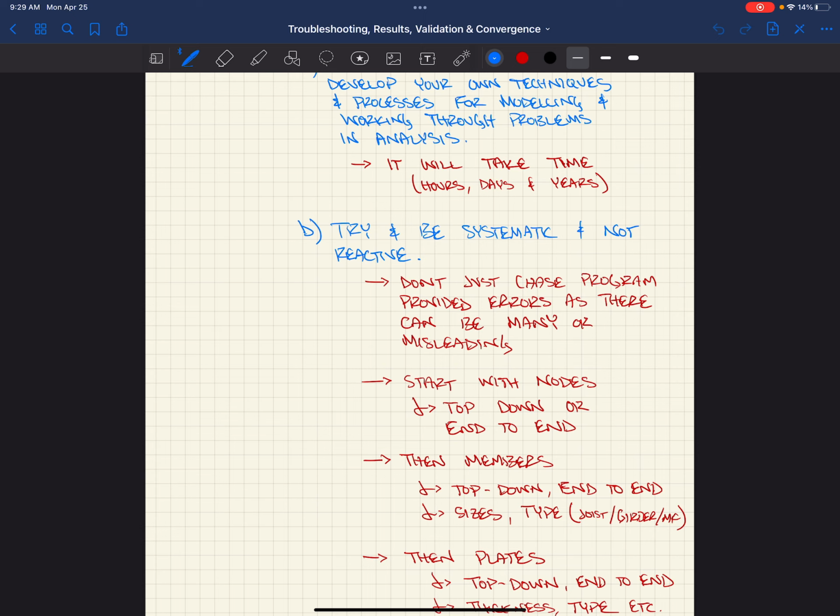Nodes. It gives you nodal information, where it's located, what types of supports it has. So if you have a lot of members that are pinned, it's going to show you that. In this case, these are all fixed, rotation and displacements. Those are pinned, rotation and X direction. Those are moment base plates or bases. So just very, very helpful. It also gives you member loads. It tells you where they're at. You can go through and figure out the service cases. Very helpful tool.